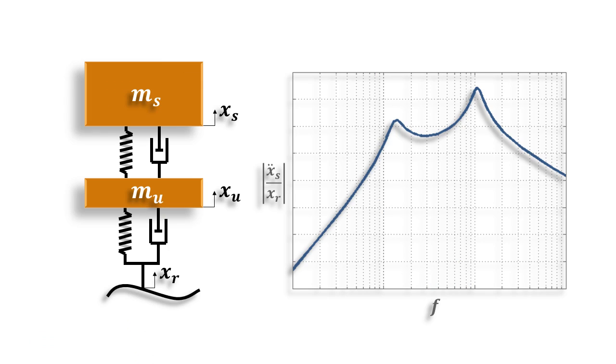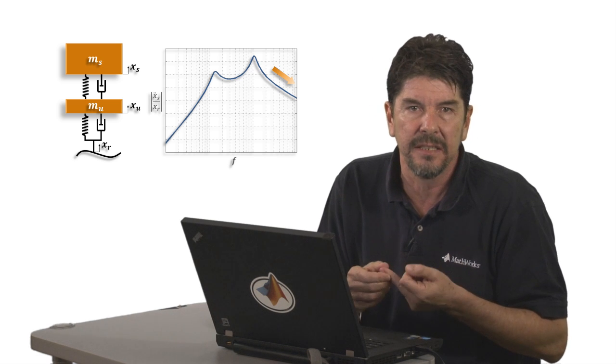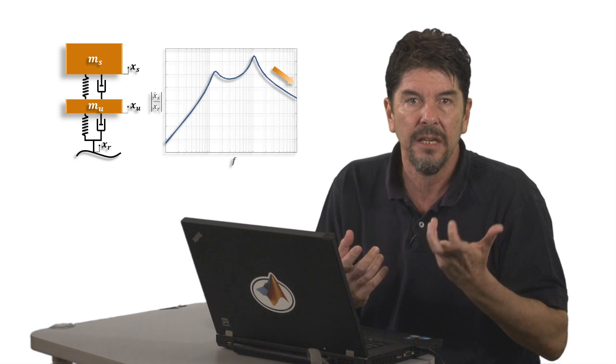And if you were on the right-hand side of that second peak to begin with, you will be climbing back up that tire resonance. I know it might sound counterintuitive, but notice that if you were to speed up instead, you will be moving further right and down that chart and the system will completely attenuate whatever disturbance is coming from the road.